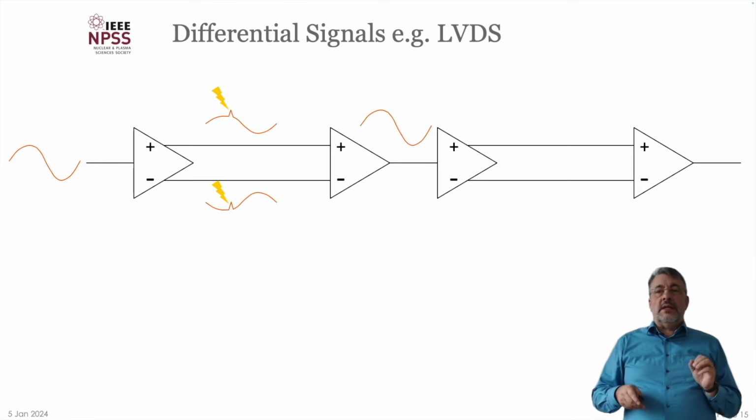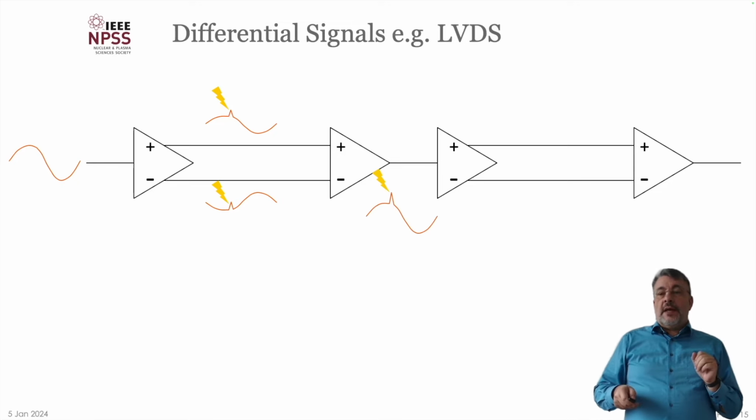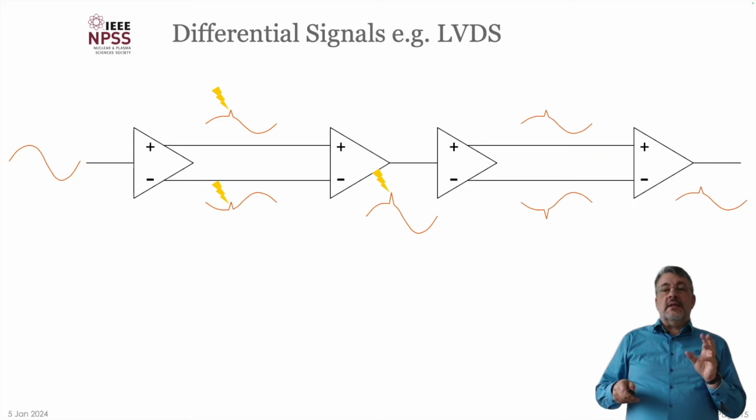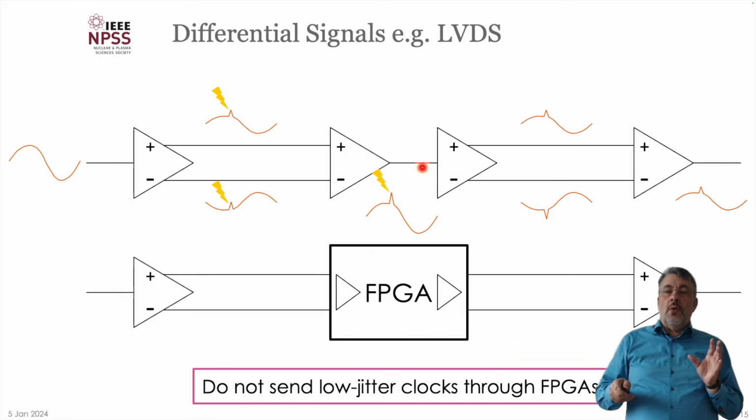There is, however, a common pitfall. You might have your signal and the inverted signal here, and again you go differentially. But if you get any noise in this little path of the signal, then the differential signal doesn't help you, because you get down here an inverted version of your noise, and if you subtract the 2 signals in the end, you get back your noise. So it's really important to have no path of a non-differential signal in between.